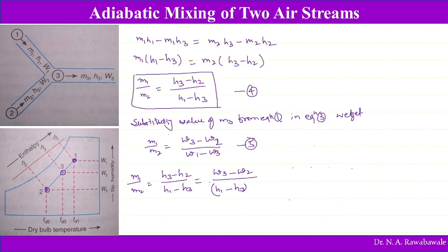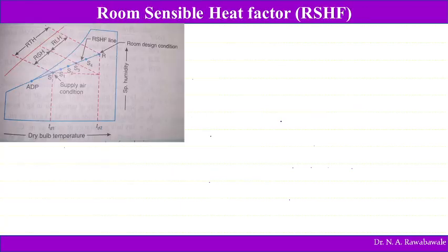Now moving to the next aspect, that is room sensible heat factor. What this room sensible heat factor is, we will discuss. So the room sensible heat factor is nothing but the ratio of room sensible heat to room total heat.